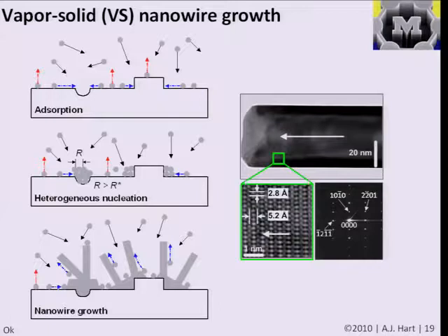And it turns out that after you go from this nanoparticle regime to, say, the nanowire regime, the same things happen, but atoms can hit the substrate and diffuse all the way along the wire and incorporate at the tips, or they can go directly from the gas phase to the tip of the wire. So that's one example, which is kind of a crossover regime between growth of a film, growth of nanoparticles, and growth of nanowires, all following this basic process in which you start with a gas phase precursor and you control the conditions so you nucleate and grow the material. And you understand how the materials stick, transport, and unstick.